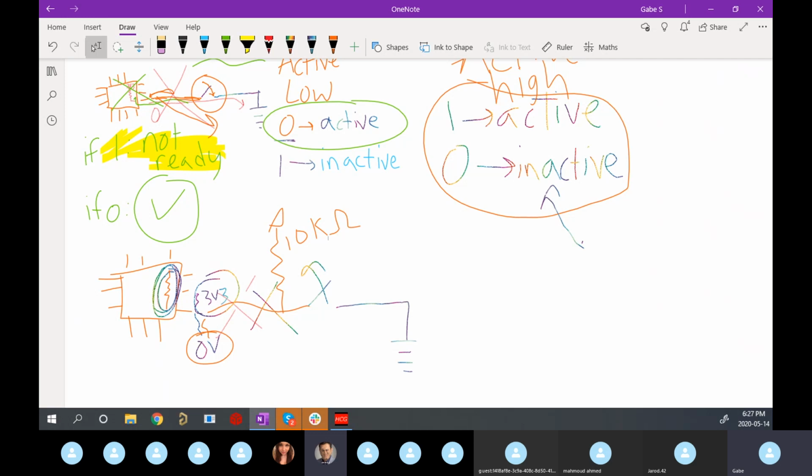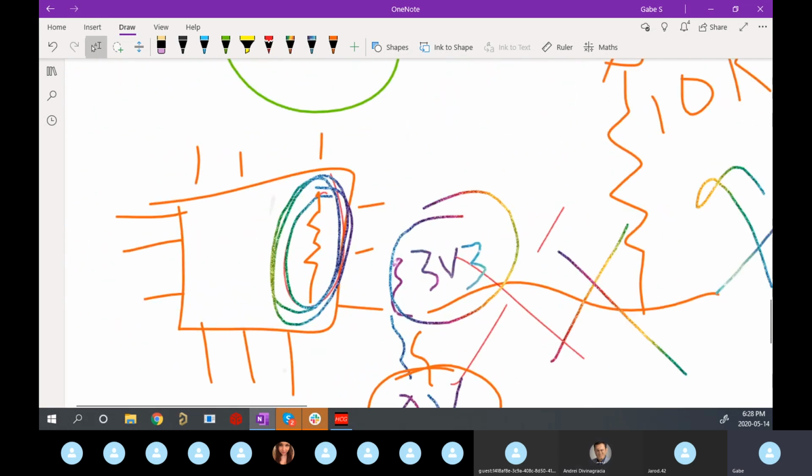When it comes to pulling up, pulling down, I guess this is more of active low stuff. Isn't there pins inside the chip itself that is automatically active high or active low? Like there's pull down resistors inside the chip, not the PCB. Yes, that's exactly right. So you can decide if you want it to be a pull up or a pull down within the microcontroller chip itself.